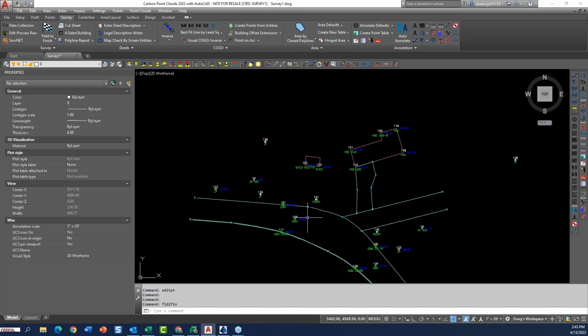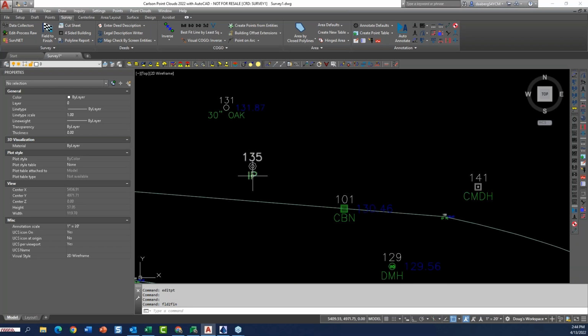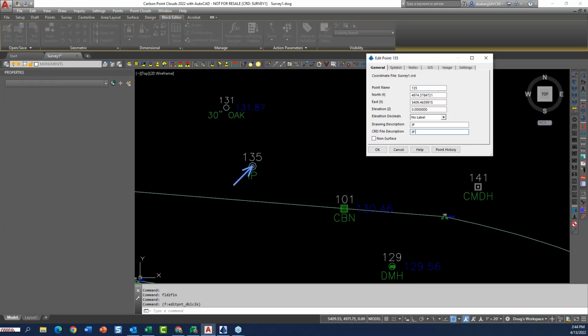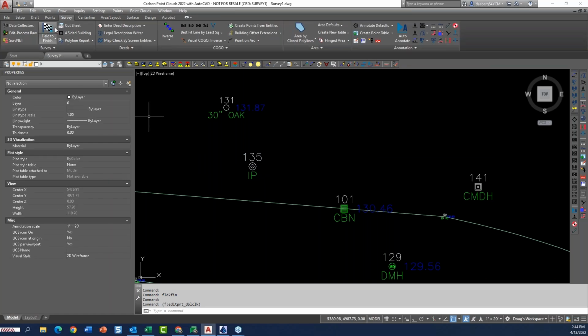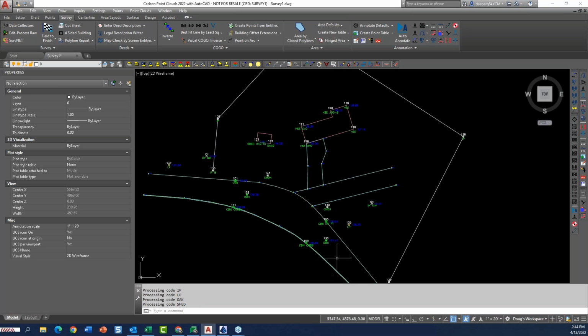But you can force line work that doesn't normally have line work associated with it by adding a beginning. So for example, an iron pipe, that's set to just be a point. If I was to say iron pipe begin, just space B, and process this, I'll actually get line work drawn around my boundary.